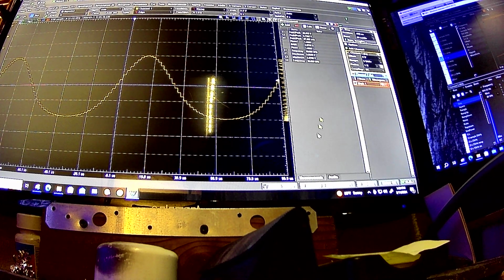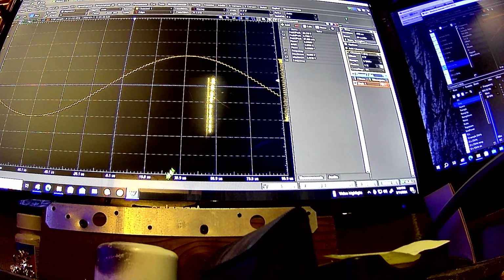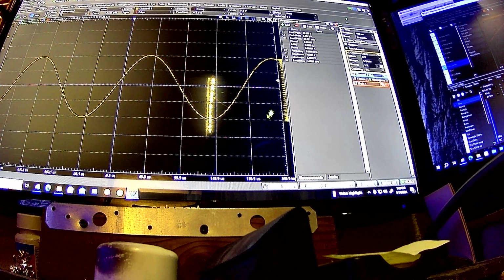Okay. But at any rate, that's again about the best you can do, and that's like a 10 kilohertz signal. Let's see. Now let's go up to 100 sample signal. So that's what a 100 sample signal looks like. But we got to adjust our frequency down to 5 kilohertz because that's going to be your maximum bandwidth with a 500 kilosample DAC.